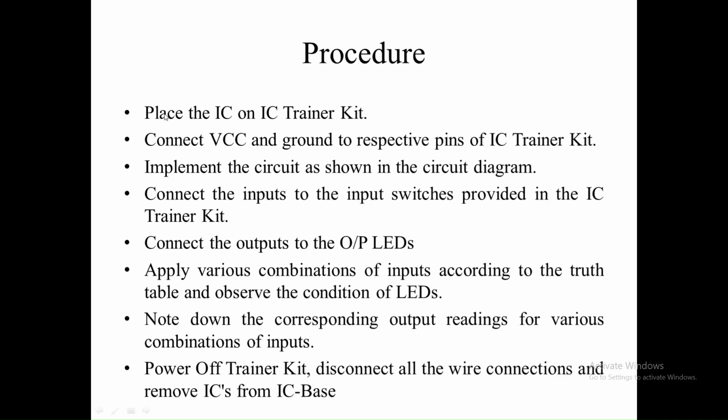Procedure: first, place the IC on the IC trainer kit. Second, connect VCC and ground pins to the respective pins of the IC trainer kit. Third, implement the circuit as shown in the circuit diagram. Fourth, connect the inputs to the input switches provided in the IC trainer kit. Fifth, connect the outputs to the output LEDs.